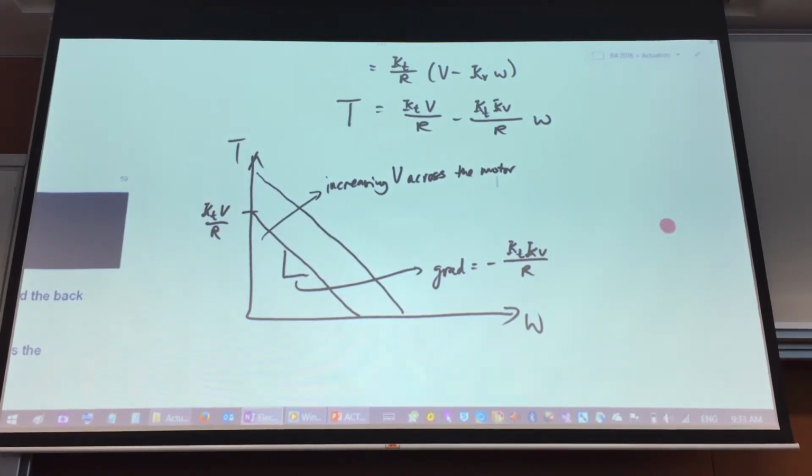As you play with the motor, you discover that there's a play between torque and speed. You very quickly discover that you get a higher amount of torque when the speed is low, preferably no speed. If you put your hand and squeeze on the shaft of the motor so that it doesn't move, you can feel quite a significant amount of torque.